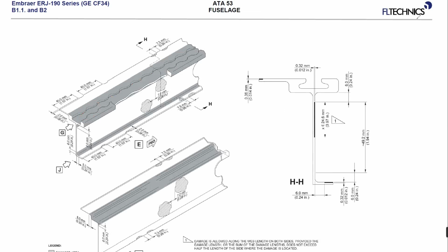But when you use metal scrapers or these metal sharp objects to remove the sealant, it's very, very easy by mistake to scratch the seat track surface or these beams. And then we have a problem. Because when you scratch, okay, the aircraft will not crash because of the scratch, but because of the scratch, you disturb the paint, also the primer layer. So now the seat track structure is exposed to the moisture in the cabin. And as I told you, sooner or later, there will be corrosion.